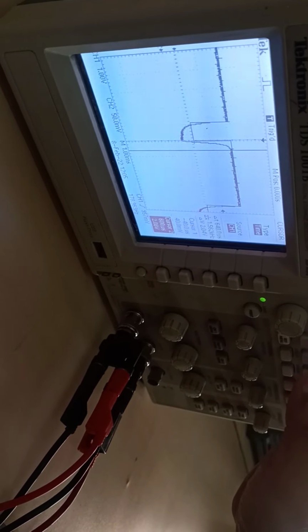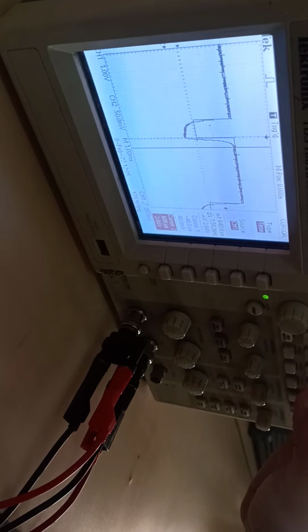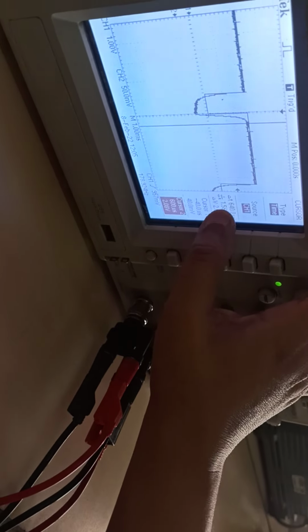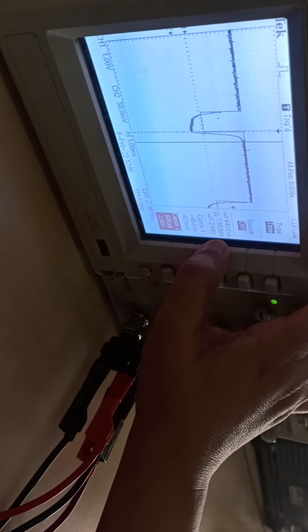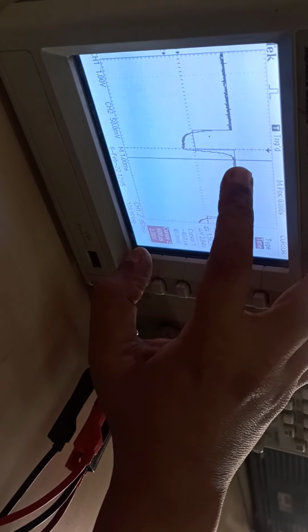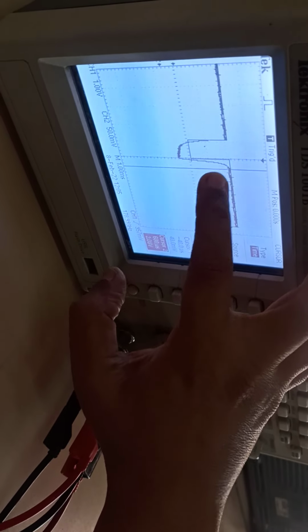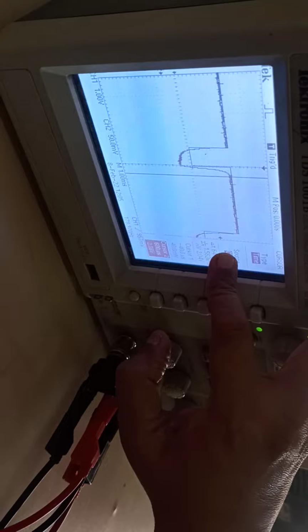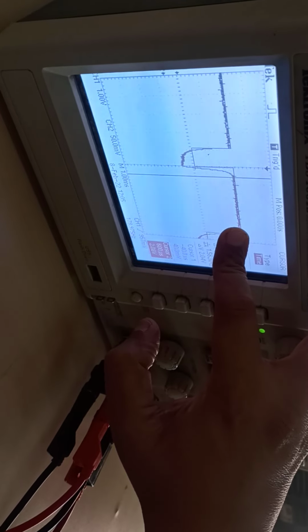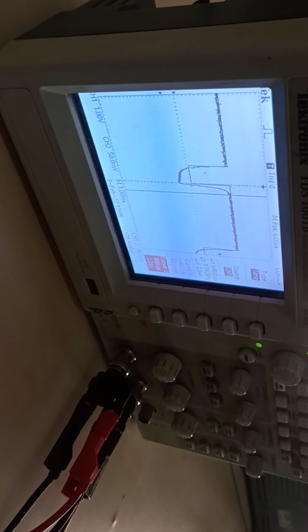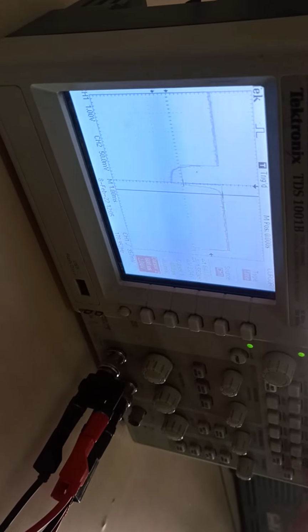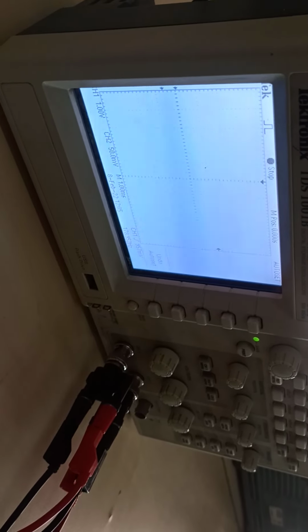So now this is using a 4K7 resistor. I am getting a 640 microsecond propagation delay to transmit a pulse. So this is a propagation delay that is going to be introduced. Okay. Now after completing this, now I am connecting the op-amp output.